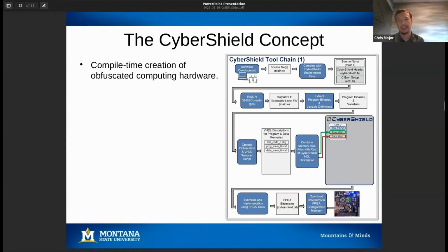And so with any similar tool chain, you usually combine that with some sort of environment file. So with Arduino, you specify the kind of Arduino you're playing with, and they give you an H file for that. Or in Code Composer Studio, you have to select a deliberate MSP430, for instance. Or if you're doing, say, PlatformIO, you bring in your configuration files so that way it knows what microcontroller you're targeting. And so now you have a proper file with your main.c, you have your library files, and on top of that, you have your runtime startup.